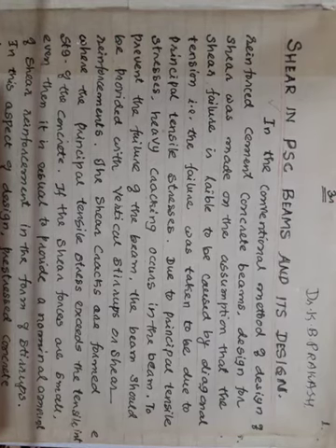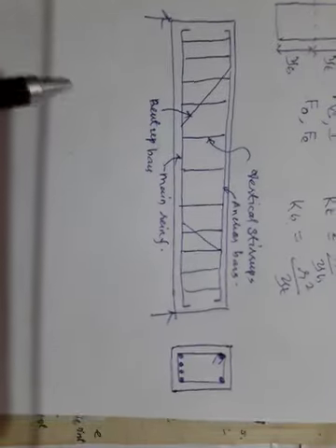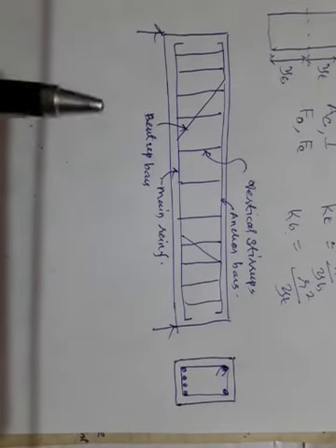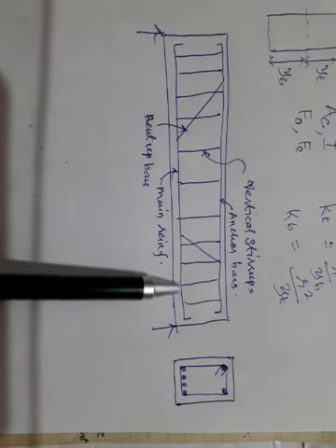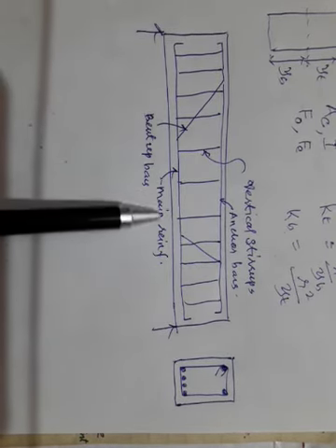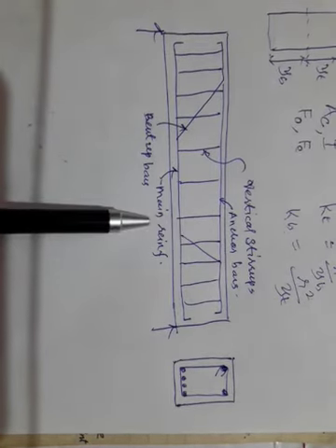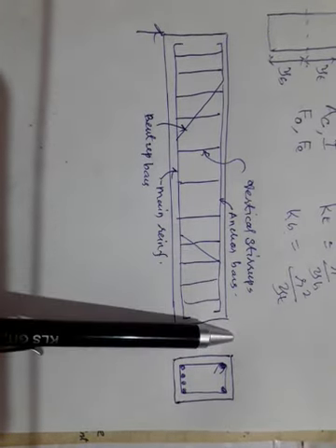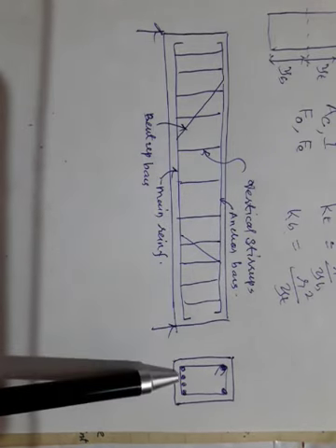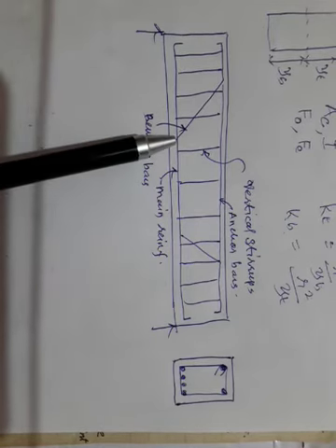So now I will first explain what exactly we used to do in our RCC. Say, for example, here I have drawn one RCC beam, wherein you know that this is your main tension reinforcement. Out of these main tension reinforcements, I may bend some bars up like this, at 45 degrees. Say, if you have got 4 bars as your main reinforcement, I may bend 2 bars up.